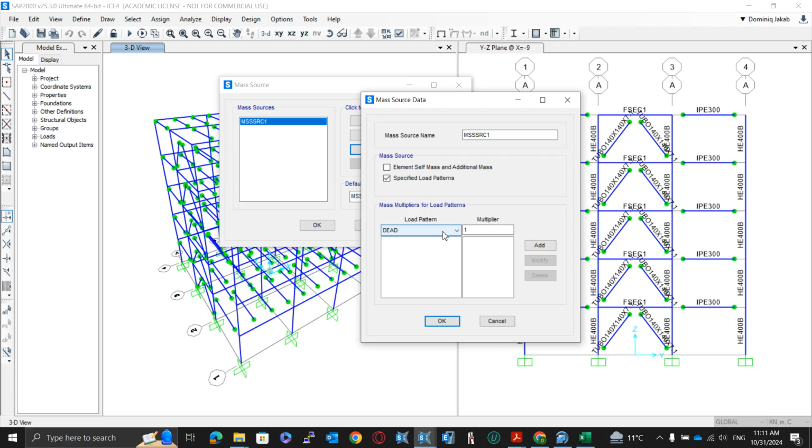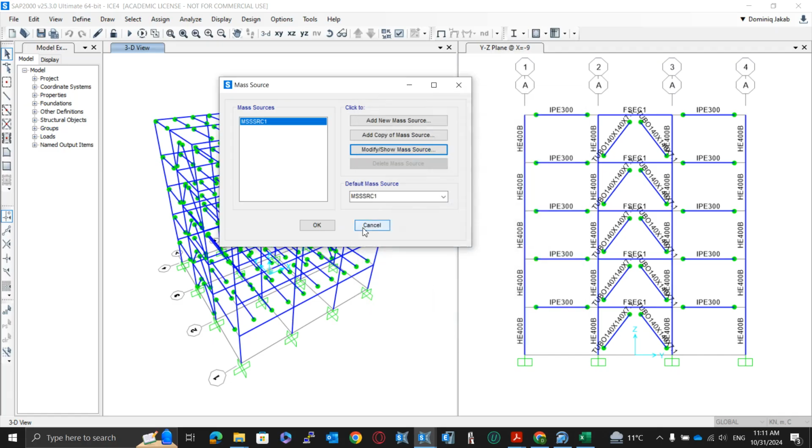The combination for the masses is basically the seismic design combinations without taking into effect the seismic load. So we have partial safety factor for the permanent as 1, for the live 0.3, and if we have snow or not, function of the roof, how it's considered, if it's open terrace or not, we go with 0.4 for snow or not. In our case, I am considering only live as open terrace, so I have 1 and 0.3 for the live load, and this is my mass.